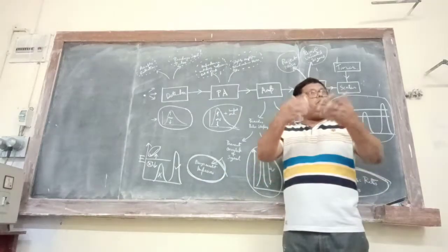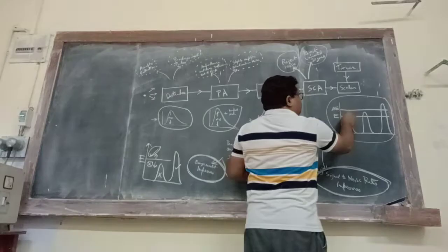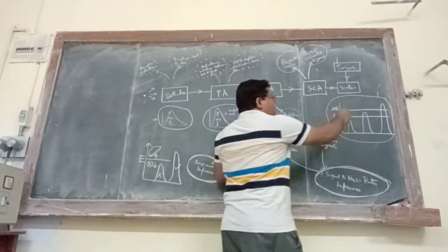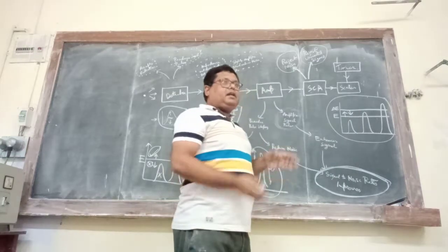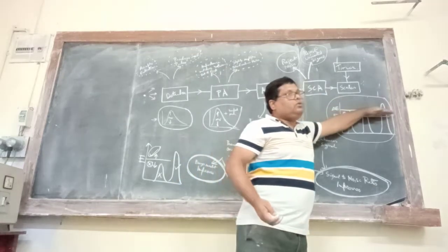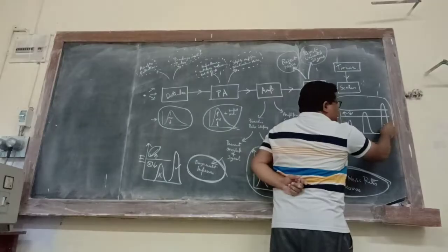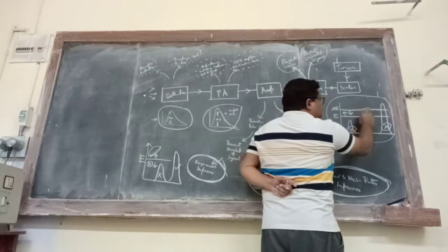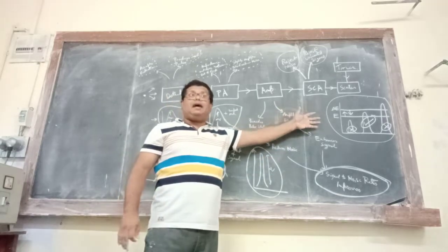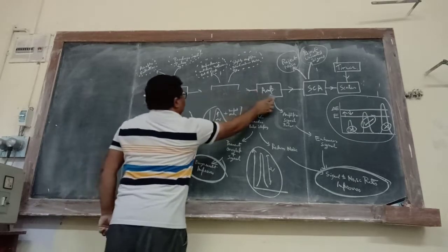Right? Now I am going to move forward and use two discriminators. Look over here. One discriminator E with the condition that accepts all the pulses which are above. And another discriminator delta E which is fixed with respect to E, and this will accept only the pulses which are below delta E. And then I will put the two in coincidence. So the result will be that I will be accepting only the pulses in this zone. So out of these three pulses, this will not be accepted, and this will not be accepted even though this is above, this is below. Only this one which is in between will be accepted. Okay? So in this way I will be able to scan the entire spectrum. How, you might ask? So let's draw this.